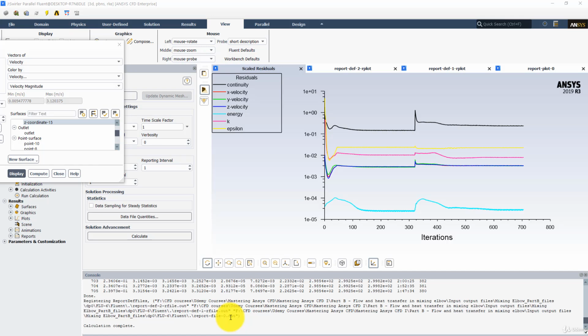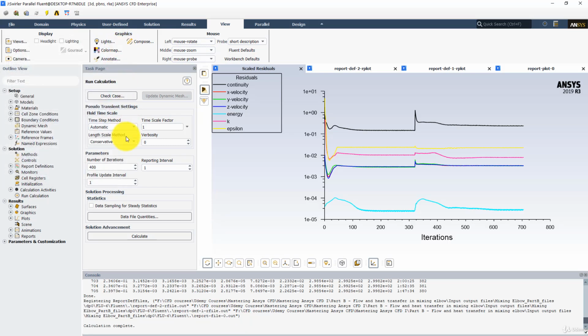So you should always run the case with the second order upwind scheme. If you go with the first order, you will have what is known as numerical viscosity, and you will see the results will be diffused, and you will not get the sharp gradients, for example for the viscosity, for the shock wave, for the density.